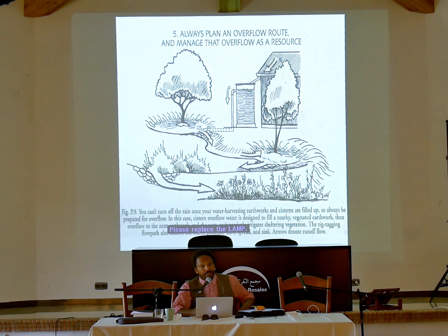Right, exactly. One risk I see with this kind of approach is that it's designed in the beginning and it's all nice and good, and then that big overflow which was designed for doesn't happen for the first 5 years, and then eventually there's a ditch and you start dumping stuff into it, so that by the time it comes to the 1 in 10 year massive rain, it doesn't work as designed anymore because you filled it up. It runs a high risk of losing functionality because it is used very irregularly.